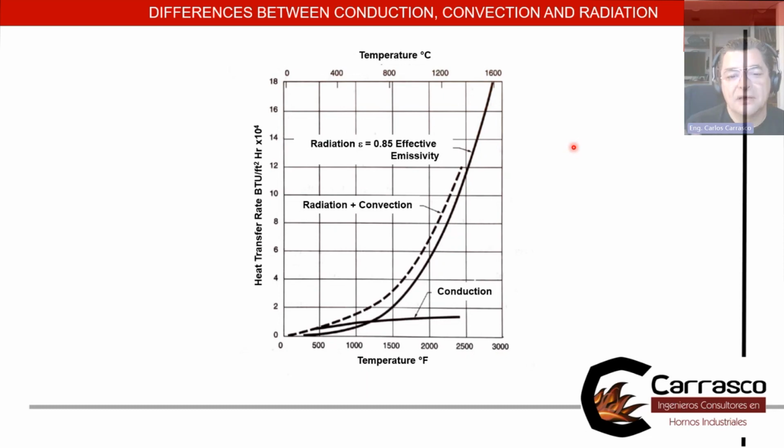So I have to consider now the load, the size of the load, the weight of the load, so I can make my heat balance and determine how much heat I have to put into the load. Then I have to consider how much volume I have to keep inside to have a properly sized furnace. Not too big, not too small.